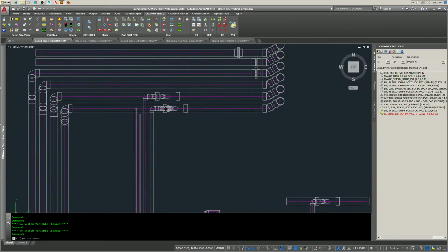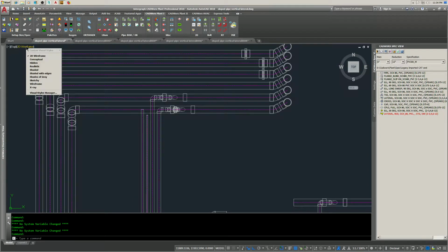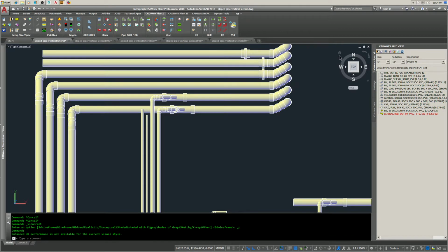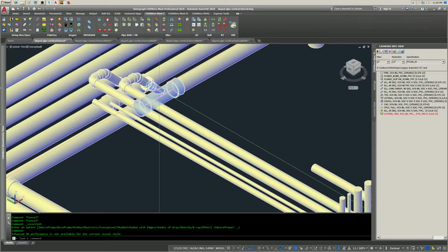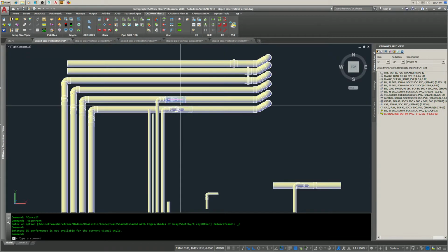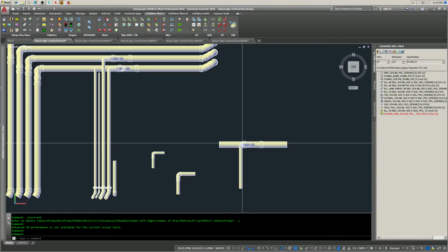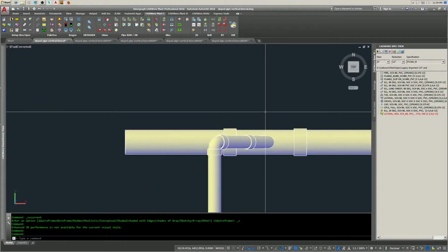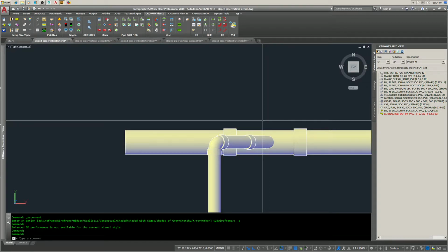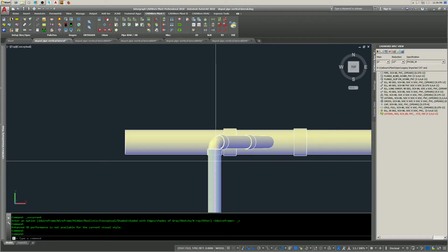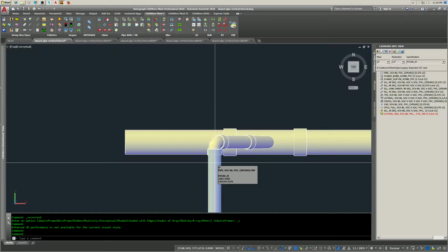Now, I did look at, there's another way of doing this, and that would be rotating this lateral in that direction 5.729 degrees, which would match the slope of this, and then you could do this arrangement just by rotating this lateral at a 5.729 degree angle, and then come off with a 90 degree, and that'll put the 1% slope on this line.